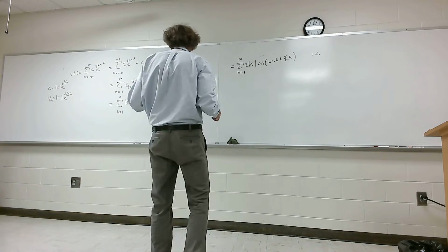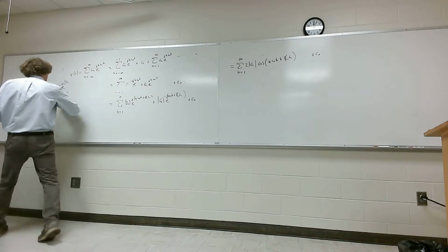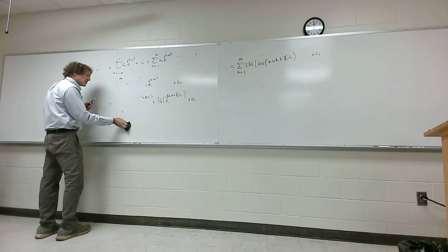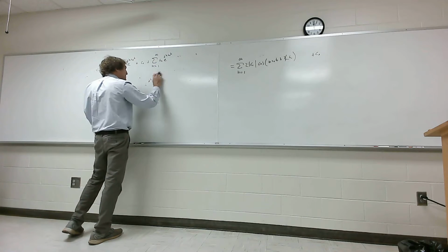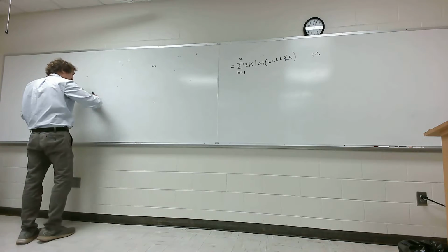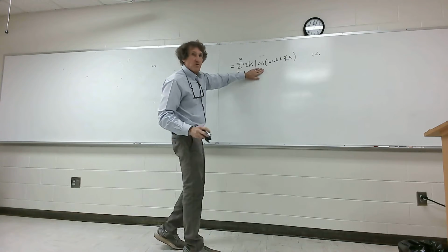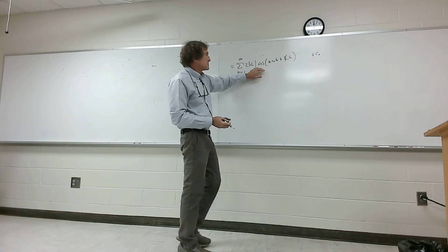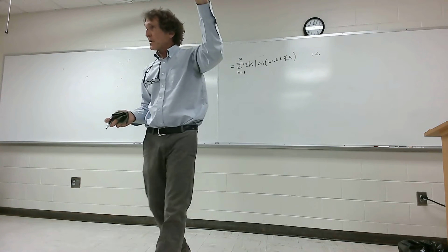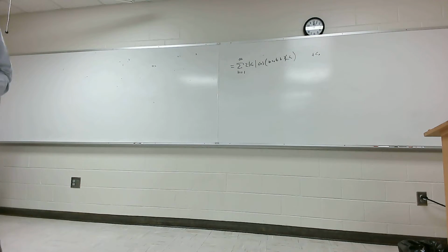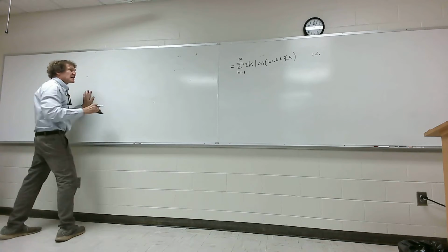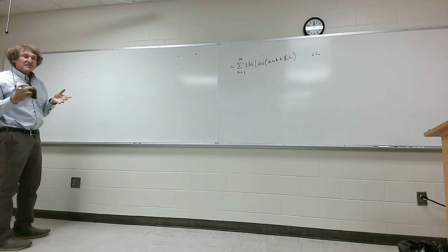Now let's put it over here. Because what do we know when we do any kind of a circuits problem with a sinusoidal or cosinusoidal excitation? How do we go about doing it? That's right. So here's what I'm saying. This form will have all the frequency components at n omega naught, all right? There'll be first harmonic is n equals 1, second harmonic n equals 2, third harmonic n equals 3, and so forth. Each one of those can be analyzed separately, its effect on a circuit, and the results summed at the end. So here's why I'm saying that.